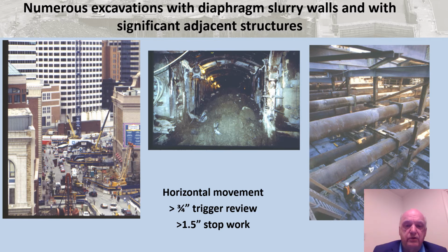Right up front, it was decided to simplify the performance monitoring so that we would limit any movement of these walls. At 3/4 of an inch, that was yellow and we'd trigger alerts. At 1.5 inches, we would stop work.